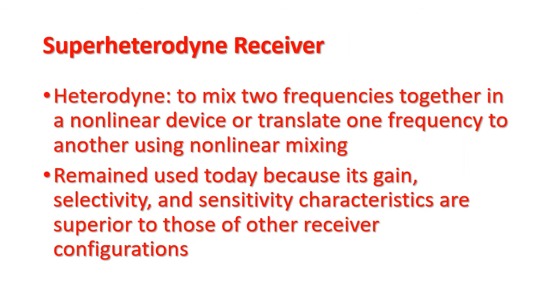Superheterodyne receiver. Heterodyne means to mix two frequencies together in a nonlinear device or translate one frequency to another using nonlinear mixing. It remains today because its gain, selectivity, and sensitivity characteristics are superior to those of other receiver configurations.